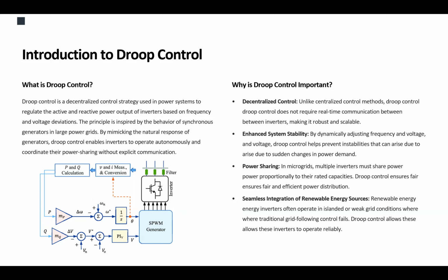That control tries to balance the electrical power that is injected into the system and the mechanical power at the output. If they are not balanced, there is going to be an increase or decrease in the speed of the rotary machine. If the mechanical load is more than the electrical load, the speed is going to decrease.